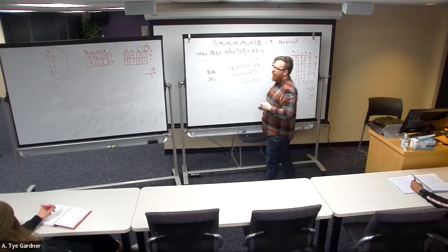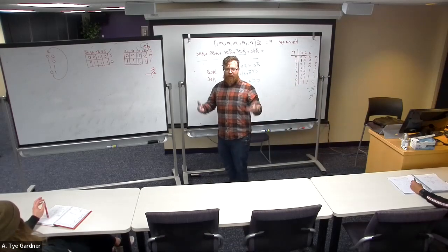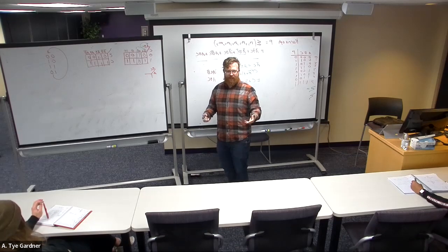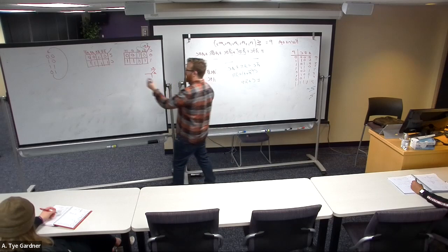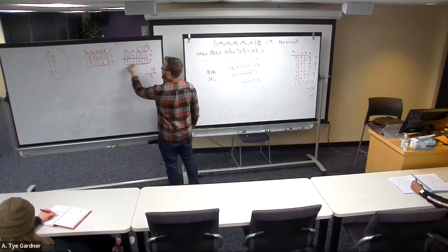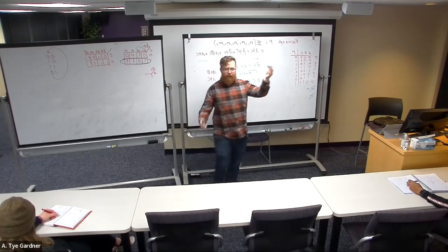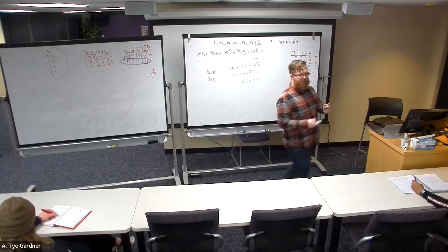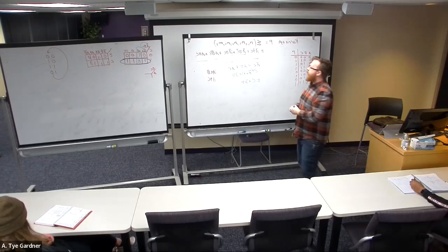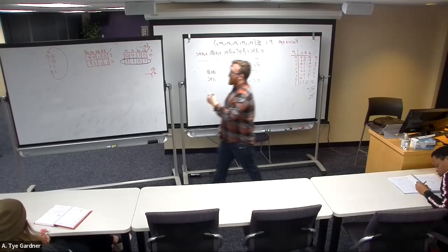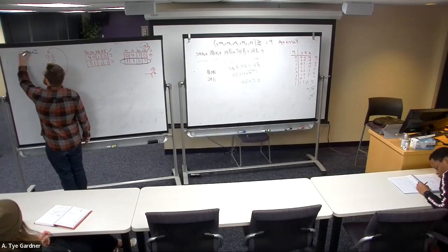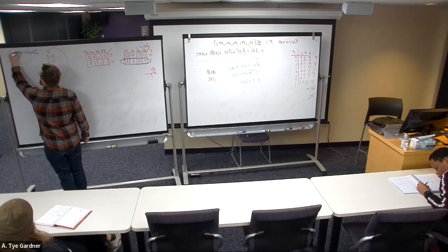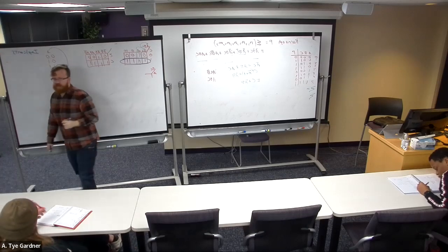Because all four of those are logically adjacent to each other, I can circle all of them together. They cooperate to simplify. It's really helpful to have many different colors in these K-maps to keep track of your circles. Your circles are things that we call implicants.